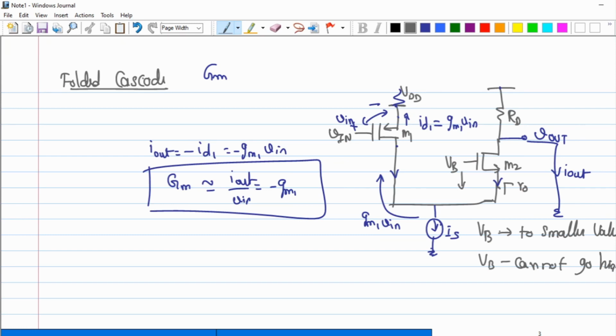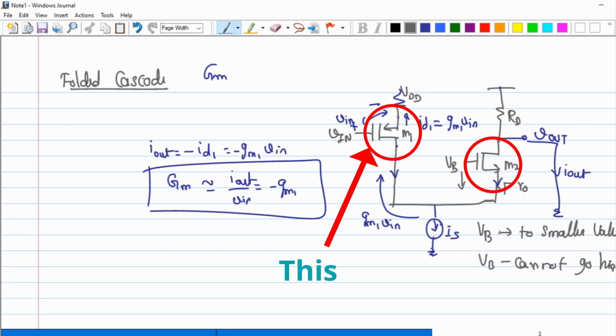Yeah, so if I replace this particular M1 with an NMOS and replace this M2 with a PMOS, then for NMOS, where's supposed to be the source terminal, source potential? Towards the ground. So obviously this transistor will be placed here, just because the source of an NMOS will be the lowest potential. So this will flip. What about this guy? When this flips, this will also flip down.